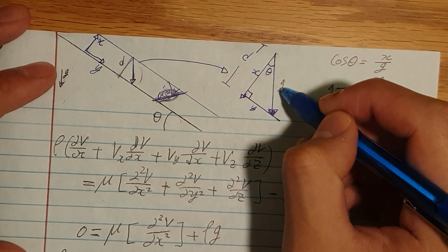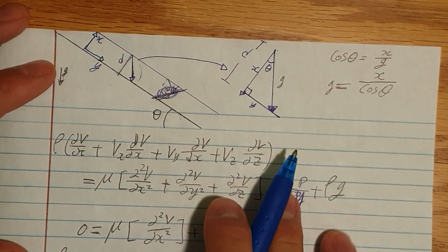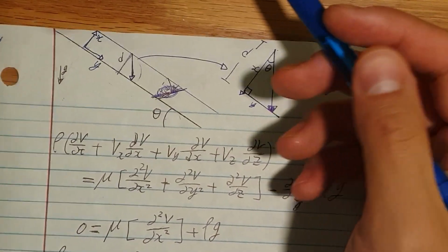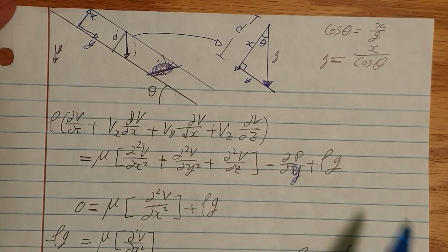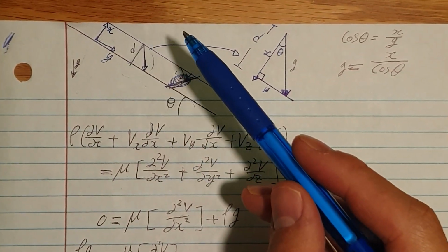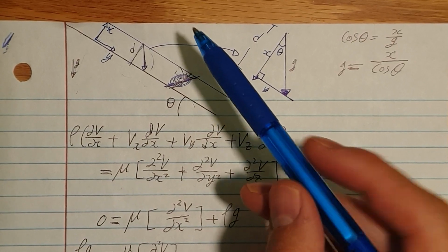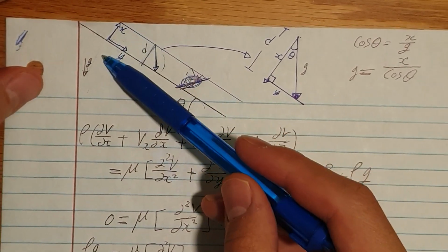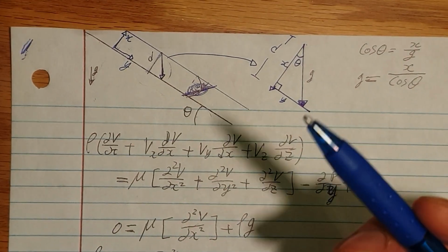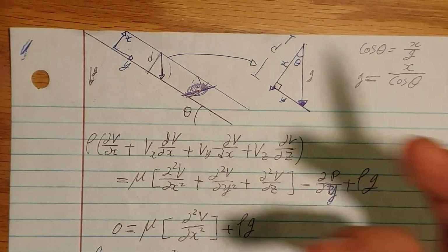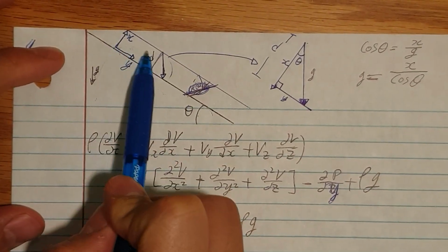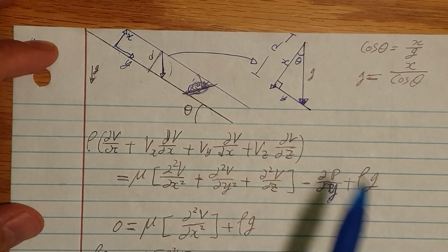And this is the effect of gravity. Okay. And so this is not pressure driven, but as you can see, this is more gravity driven. Among rectangular coordinates and cylindrical coordinates, we know this is rectangular because we're using x and y, and this is not a pipe flow. Now we have to choose in what direction the fluid is flowing. The fluid, of course, is going to flow this way, in the y direction.